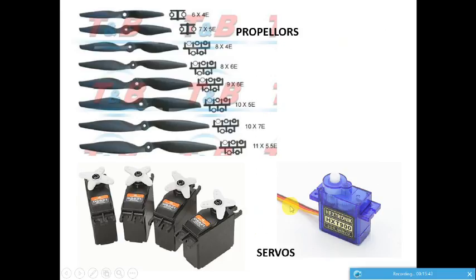Okay. Another main thing without which an aircraft cannot move is the propeller. The propeller has different dimensions and different pitch angles. The ones we used in our model were 9x6 and 9x4.5. I think 9x6 is here.